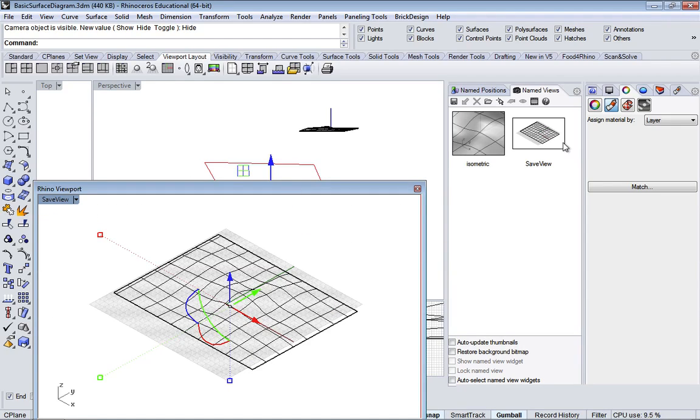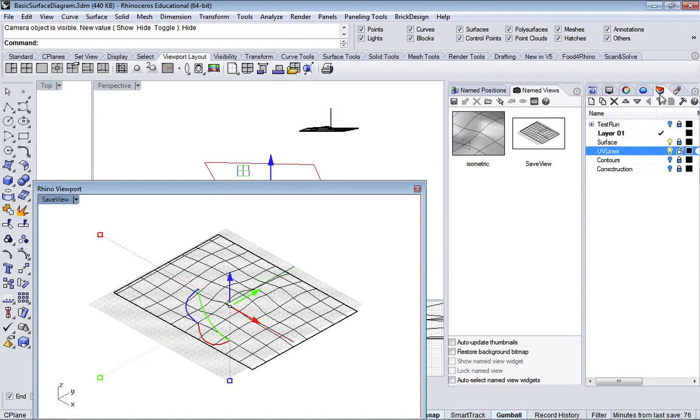So the next thing we need to do is go back and organize, because that viewport, we want to have it on its own layer. So let's go over to our panels on the right hand side, click on the layers, which is the multicolored pie, looks like a French flag. And then we want to create a new layer, so we go up to there. Oops, I created two. I got a little antsy. I'm going to select this one, delete. And select this one, and I'm going to click in here, kind of double clicking to change this, and we're going to call that viewport outline.